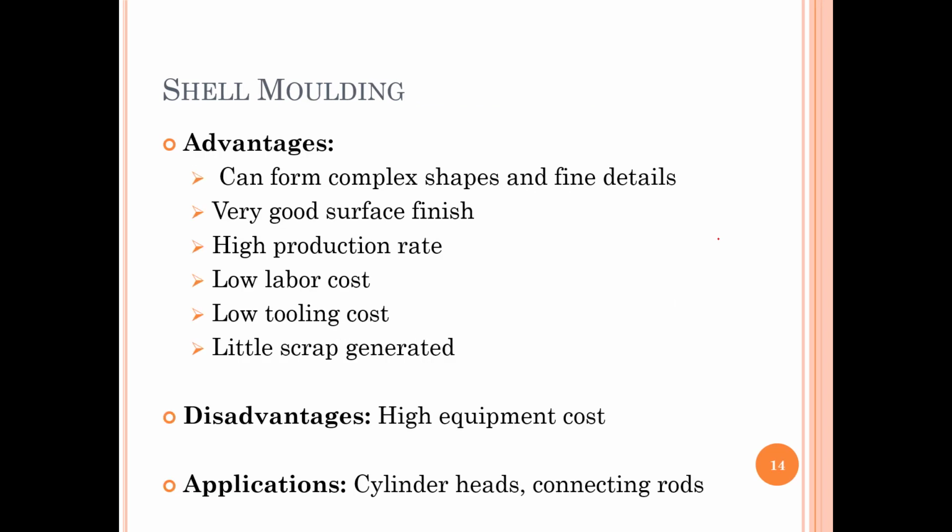Advantages of shell molding: complex shapes and fine details we can get, good surface finish, we can obtain a high rate of production, low labor and tooling cost, little scrap generated. Disadvantage: high equipment cost. Applications are cylinder heads and connecting rods, etc.